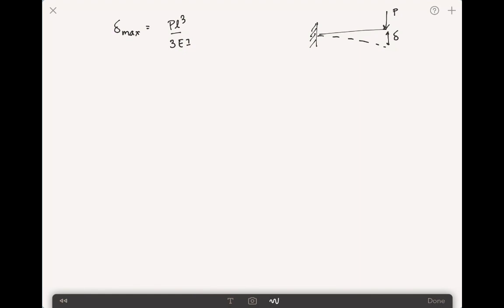This is just a bending beam, so we can just write that Euler-Bernoulli principles apply here. But if you have a thick beam, then you have an additional term given as shear strain, shear stress that comes inside. So there is a shear which has to be added to this equation here, and it doesn't remain as simple as this one.